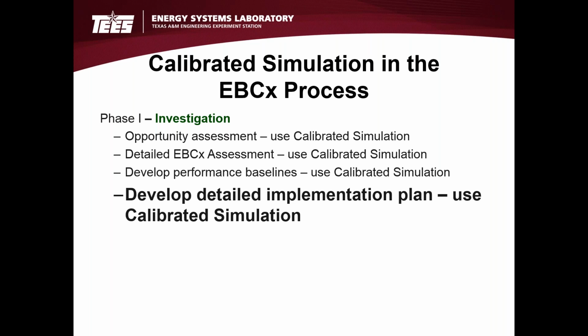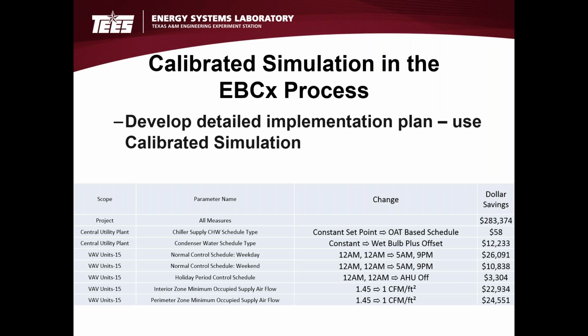But one of the things that's very useful here is that once you have that calibrated simulation model from the assessment, you can basically take that model and refine it based on your findings from more detailed measurements and your site visits, and you come up then with what we might say is a site verified calibrated simulation model, and we have our program set up so that we can then input into it basically any kind of operational changes that we want.